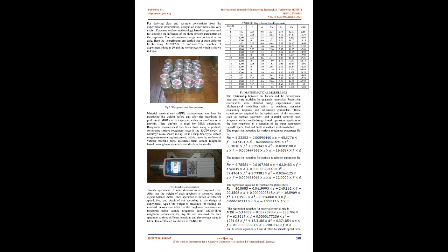Response surface methodology was used for optimization by taking cutting speed, depth of cut, feed rate, and nose radius as cutting parameters. Optimum cutting parameters obtained for multi-objective optimization were 210 m/min, 0.16 mm/rev, 0.42 mm, and 0.40 mm for cutting speed, feed, depth of cut and nose radius respectively. Ashok Kumar Sahu et al.